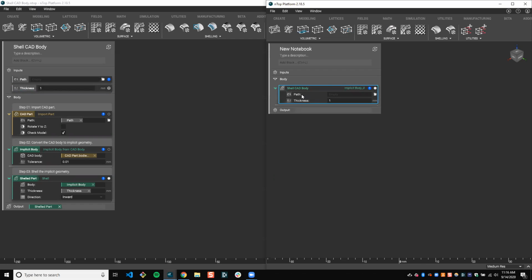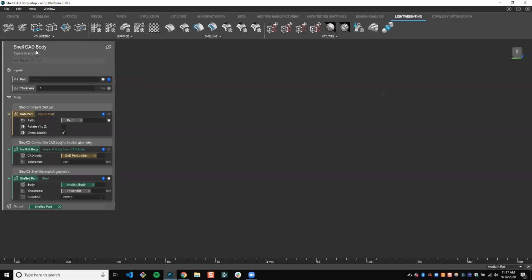Let's take a look at what we can do now to improve this. Now we know more or less how to set up a workflow so that it can be imported as a compound block. And I've shown you the process of actually importing that notebook as a compound block. And so why I was saying it's important to save your nTop file as your notebook name, if you're intending to use the nTop file as a custom block, is because I could call this whatever I want.